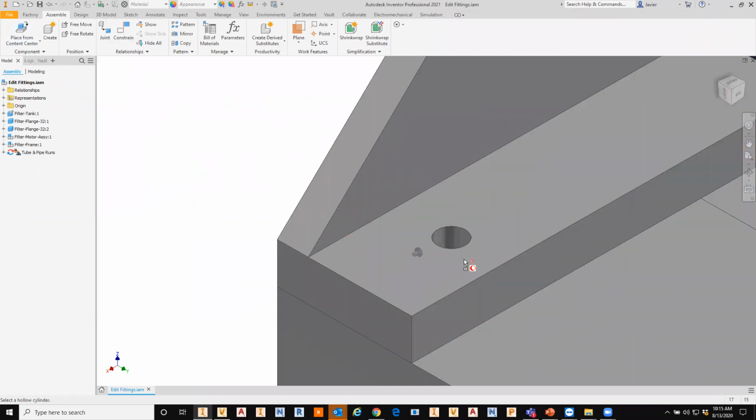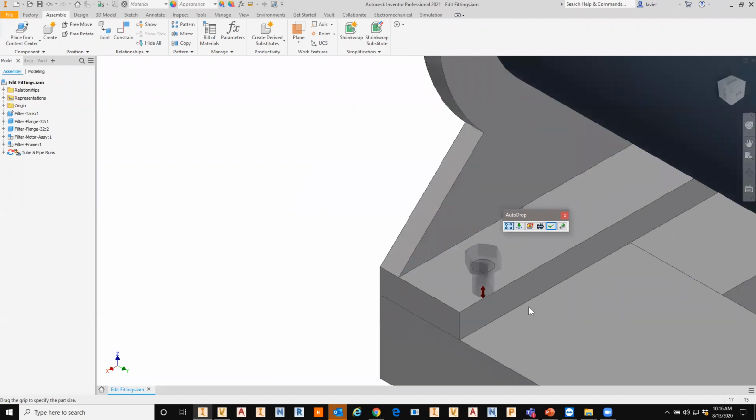You can see for this hole, this default fastener is not the right size. If you sit on this for just a second, it'll go and find the right size based off of that nominal diameter. So again, you sit on that arc or circle, it reads the nominal diameter and says, hey, you probably need a 1/2 inch fastener. You could just place it out in space and click and then add constraints. But some of these advanced placement options make it really easy to just click, and it's already constrained. There is an insert constraint already added in there.